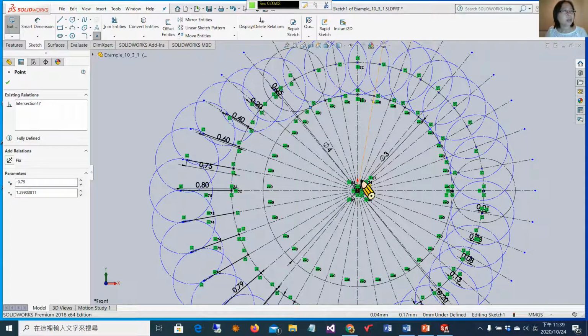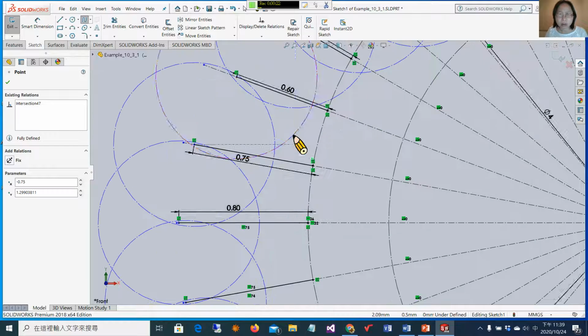Then I draw a curve tangent to the roller positions to get the work curve. It is also the cam profile. I use a spline and select the tangent positions.